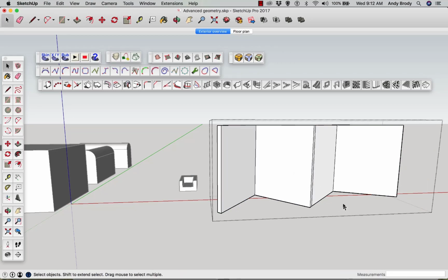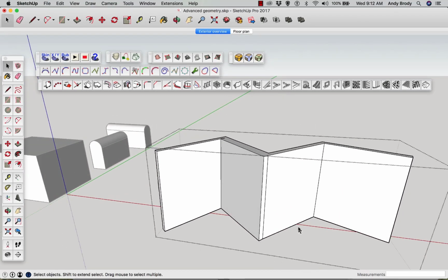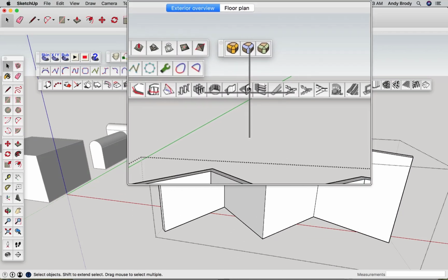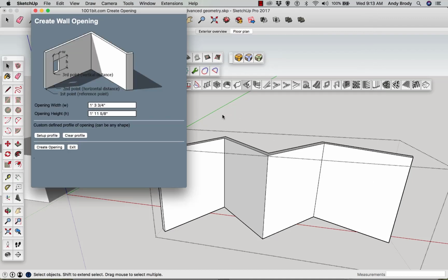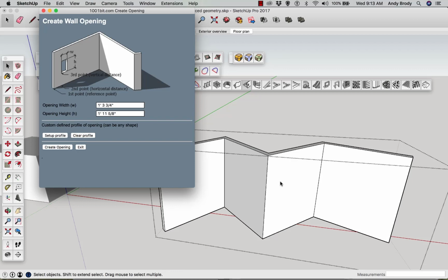and the pieces are available for editing if the geometry allows it. Anyway, the thing that's really cool about these walls is it also has a make a hole in a wall tool here, and it looks kind of like a little window opening. And when you use SketchUp components, normally they cut through one surface but not two. So this make a hole in a wall tool is super handy because it cuts through both surfaces. It poses certain problems if the component doesn't have anything to go into.